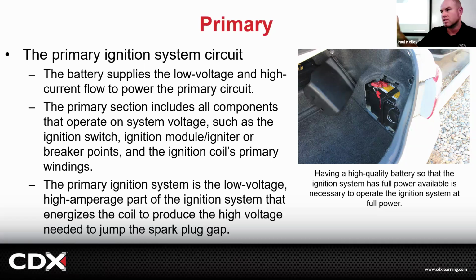Close. The dwell time could be the same, but it will try, but it has a limit. If you only have 11.9 volts and you were expecting to have 13.9, that lower primary voltage is going to be equal to a lower secondary voltage.